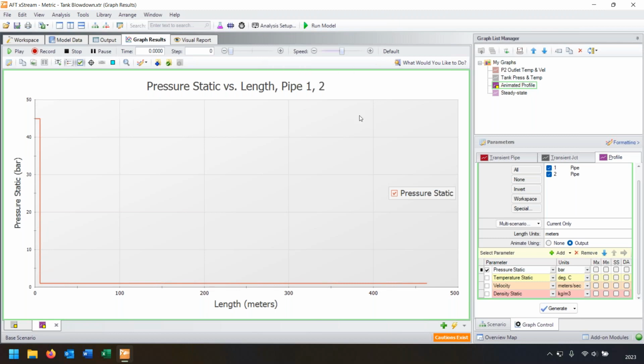So we can go time step by time step. So here, if you look at this time up here, as we open the valve, we see the pressure decrease along the line. So our tank is maintaining its pressure so far. We're seeing an increase in pressure here as it's going through the valve. The valve is still very closed, so there's still a very high pressure loss, but as the valve opens more and more, we see lower and lower pressure loss through the valve.